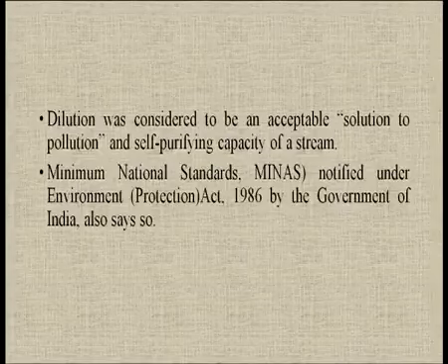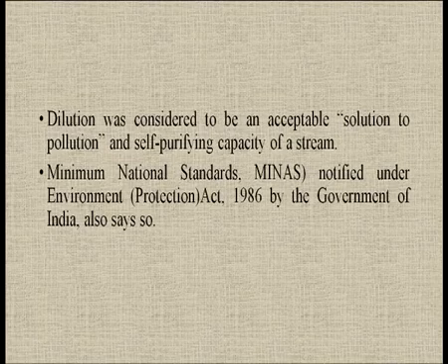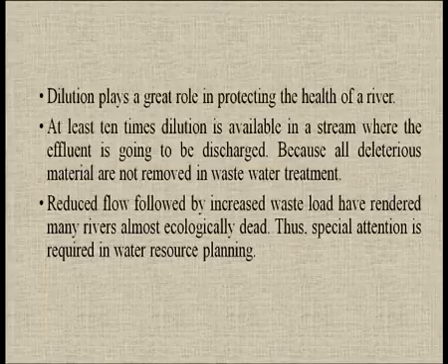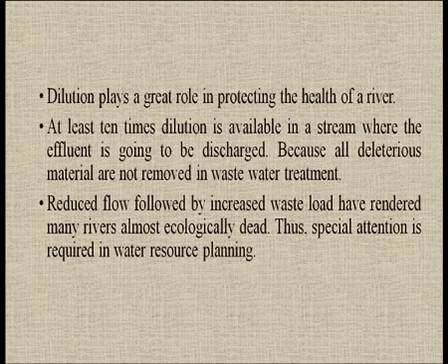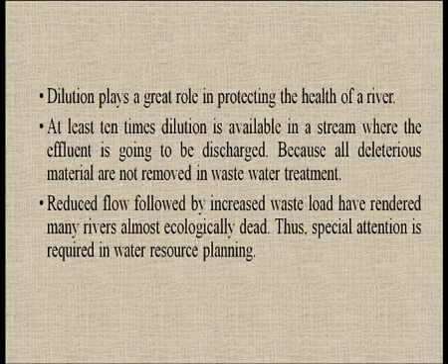Minimum National Standards, which is also called MINAS, notified under the Environment Protection Act of 1986 by the Government of India, also says so. Dilution plays a great role in protecting the health of the river. At least 10 times dilution should be available in the stream where the effluent is going to be discharged, because all deleterious material is not removed in wastewater management.